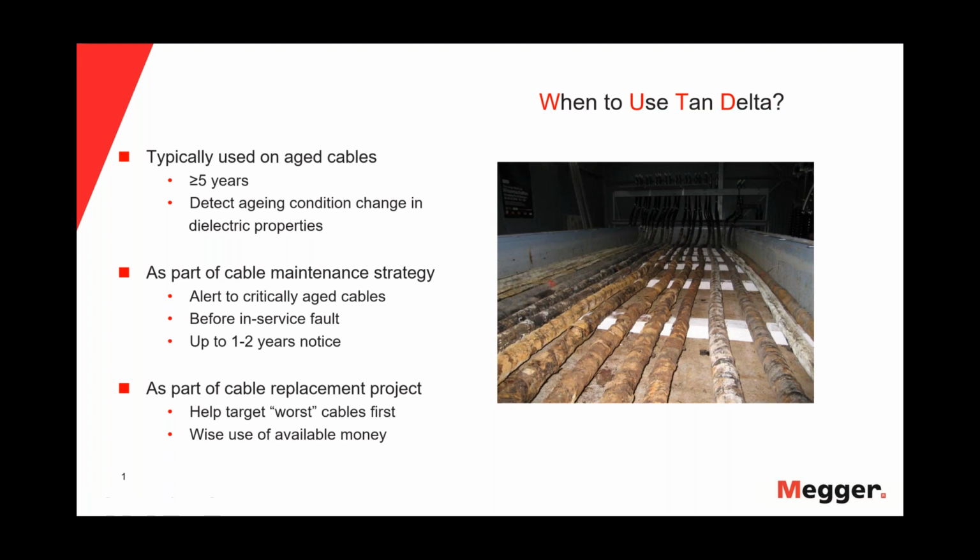So thank you, Javier. Thank you, Michael. Thank you, everybody, for joining us today. What we're going to do is go into when to use tan delta. Of course, it's typically used on aged cables, 5 years and greater, and we also use this to detect aging conditions and changes in dielectric properties of these cables.